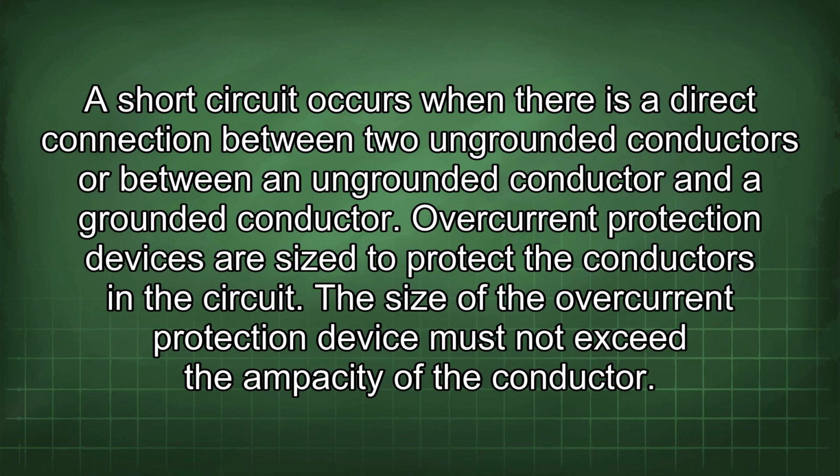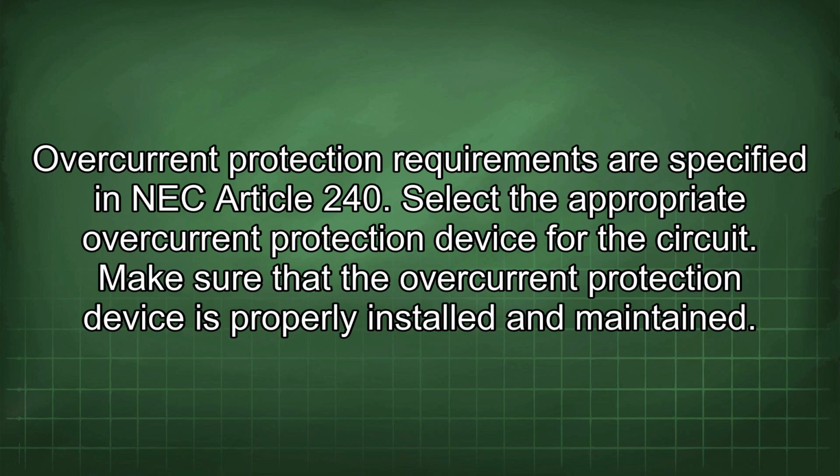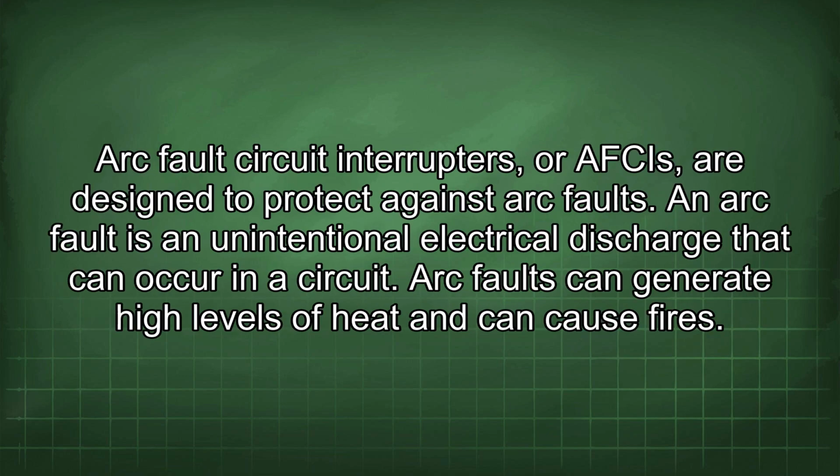The size of the overcurrent protection device must not exceed the ampacity of the conductor. Overcurrent protection requirements are specified in NEC Article 240. Select the appropriate overcurrent protection device for the circuit. Make sure that the overcurrent protection device is properly installed and maintained. Arc fault circuit interrupters, or AFCIs, are designed to protect against arc faults.